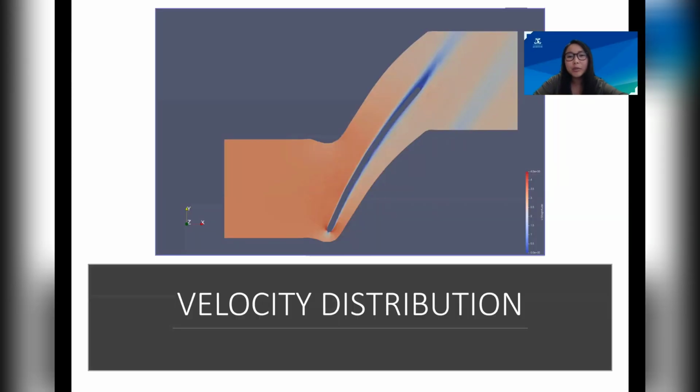Computational fluid dynamic simulation was run through a program called OpenFoam, utilizing the K-Omega SST turbulence model to solve the Navier-Stokes equation. The simple foam solver was utilized, which is the steady-state solver for incompressible turbulent flow. The initial conditions imposed in the CFD case are in reference to the values experimented by the previous year's capstone team of a low velocity of 3.3 meters per second.